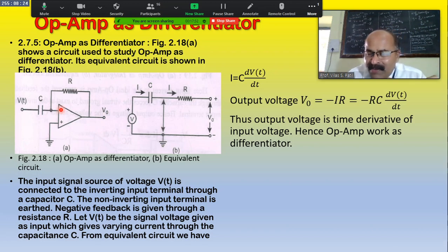In the case of negative feedback, the phases of input and output are 180 degrees out of phase, opposite to each other. If the input is in the positive half cycle, the output will be in the negative half cycle. How much phase difference was observed here? 180 degrees out of phase. If the input and output come 180 out of phase, that feedback is known as negative feedback, and in negative feedback the amplitudes are subtracted.